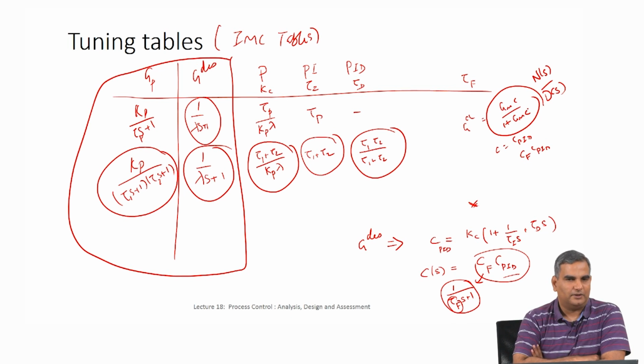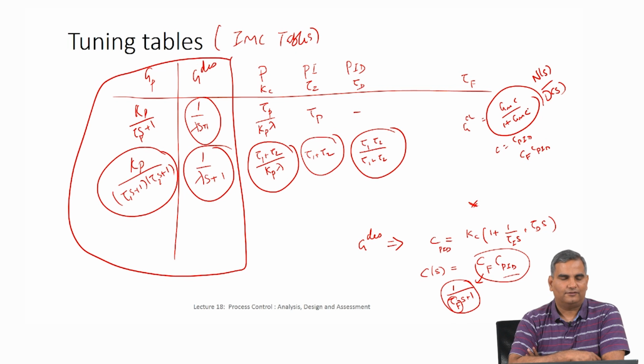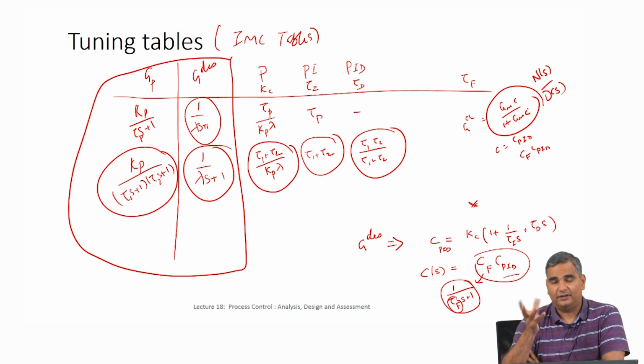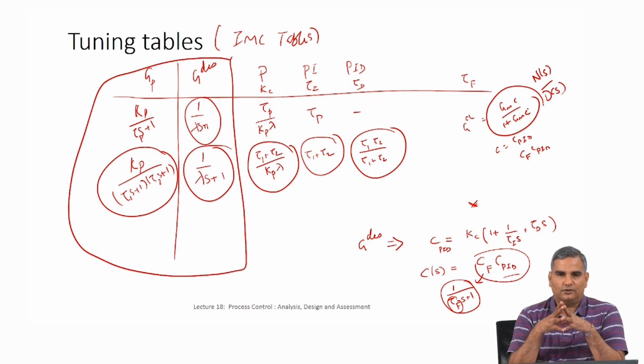All of that to some extent depends on the design that you have. So if you have a particular line where you put in a valve, flow in could become a manipulated variable. But if you had a valve but you didn't manipulate it at all, left it at only one position, then it can actually be a disturbance variable. So it is important to understand conceptually what these mean, so that when you look at the design you are able to see where I can manipulate the variables, where I have to treat variables as disturbance variables and so on.